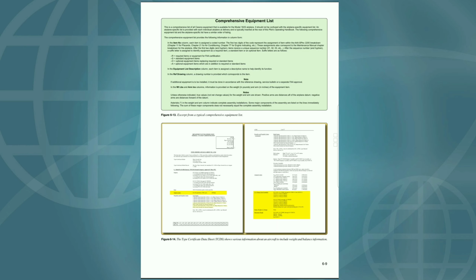1 Hartzell hub model HCC2YK-2CGF, blade model F C7666A. This model includes the Hartzell damper. Or 1 Hartzell hub model HCC2YK-2CGUF, blade model F C7666A. This model includes the Hartzell damper. Note: HC2YK may be substituted by HC-E2YR per Hartzell Service Advisory 61.